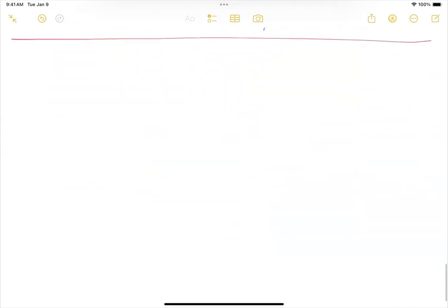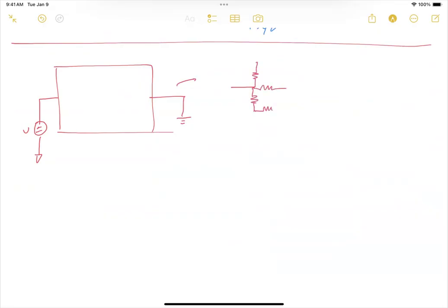There are also other ways that you can think about this problem. Another way to solve this problem is to take the voltage plane and divide it into a bunch of infinitesimal resistors, which are connected in series and parallel in a grid form like this. This grid extends all the way to the other side, with the same kind of repeating structure, and so on.